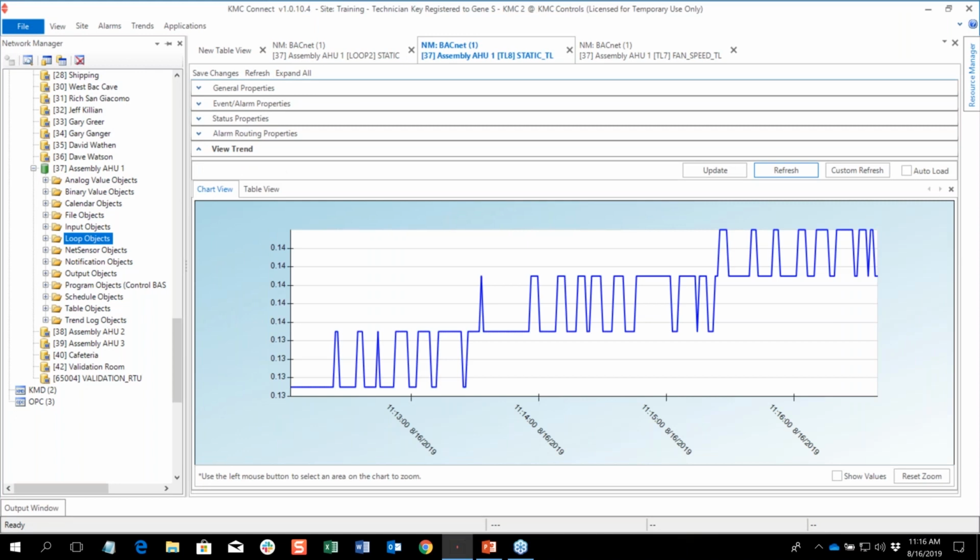Question that just came through on the Conquest Series VAV: the application comes with hours defined for reset and 0 in the terms. I should mention that generally, while the controllers are all capable of PID, for ease of troubleshooting we generally default the terms to proportional only. If there is an I term, then we're probably going to start with something fairly conservative. Again, that 4 resets per hour for temperature, and then you could adjust from there.